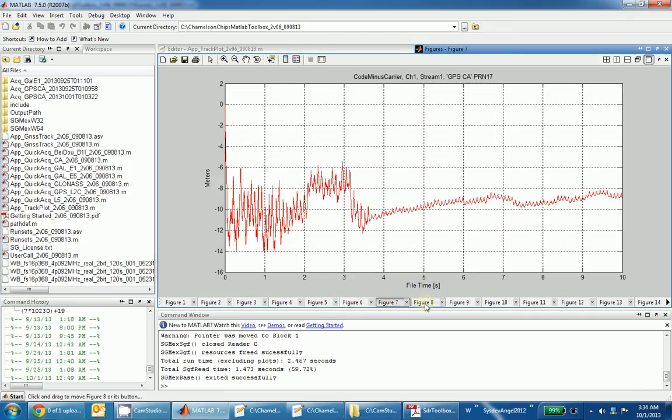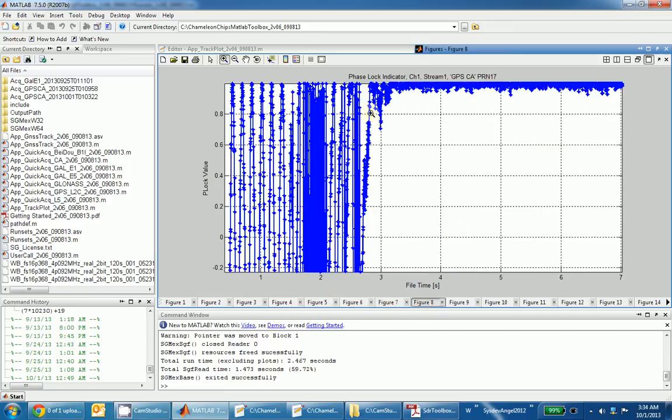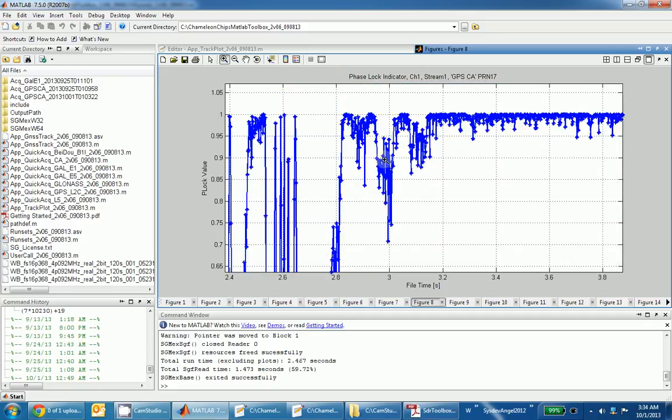And so you can see here that this is the timeout, and then somewhere over here it reached the point, the indicator went to above 0.9, so that's probably somewhere over here, and then as a result it snaps to a phase lock loop. It basically turns off the frequency lock loop discriminator, and as a result there's very little that the tracking loop has to do to correct itself to go to a phase lock loop mode.